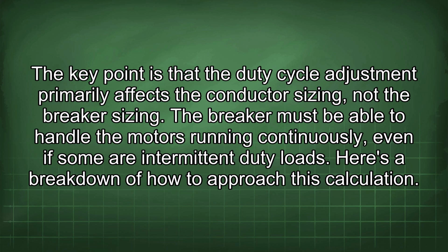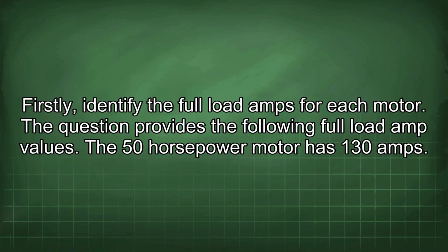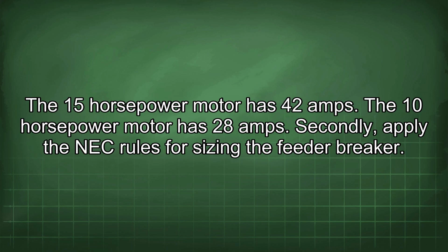Here's a breakdown of how to approach this calculation. Firstly, identify the full load amps for each motor. The question provides the following full load amp values. The 50 horsepower motor has 130 amps. The 15 horsepower motor has 42 amps. The 10 horsepower motor has 28 amps.